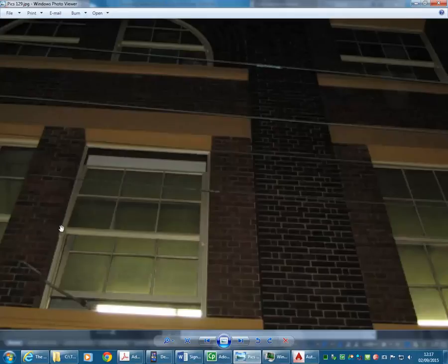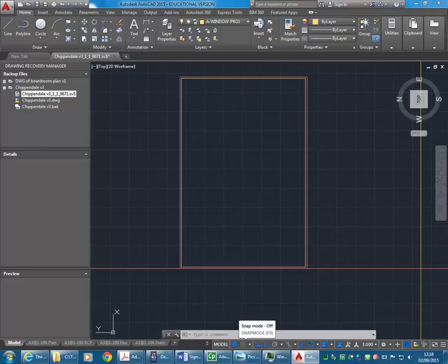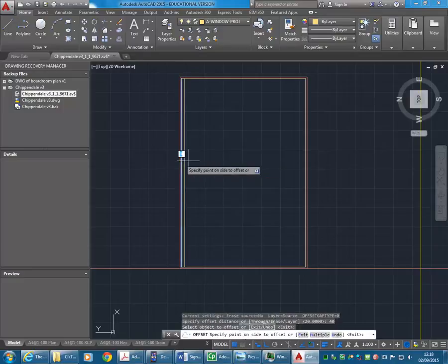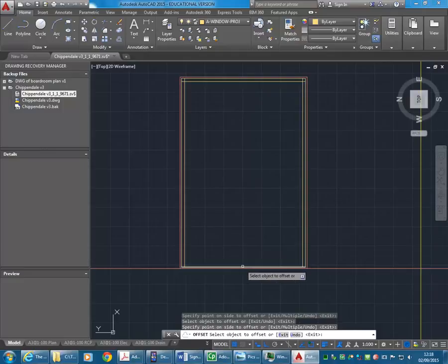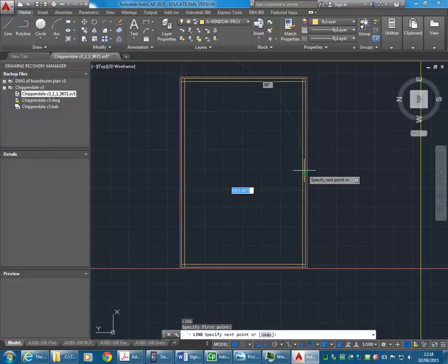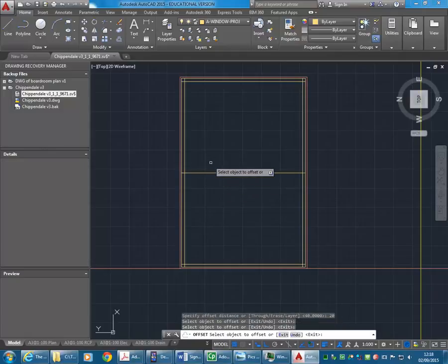So again, here I'm just going to say 40 mil for the sash coming in. And once you've seen how to draw one of these, then you can easily work out any sash window. They're all basically the same. So coming across the midpoint there, I'm going to assume that the sill of the bottom piece of the sash is also 40 mil, so there'll be 20 mil either side, above and below.